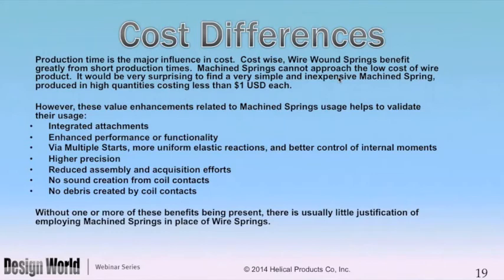And so the cost of a machine spring can be considerably more. 10 times maybe not enough. But to support this higher cost, one needs to look at why the machine spring could be of value. The integrated attachments is certainly one. The enhanced performance, we'll talk about that, due to multiple starts or some other features.